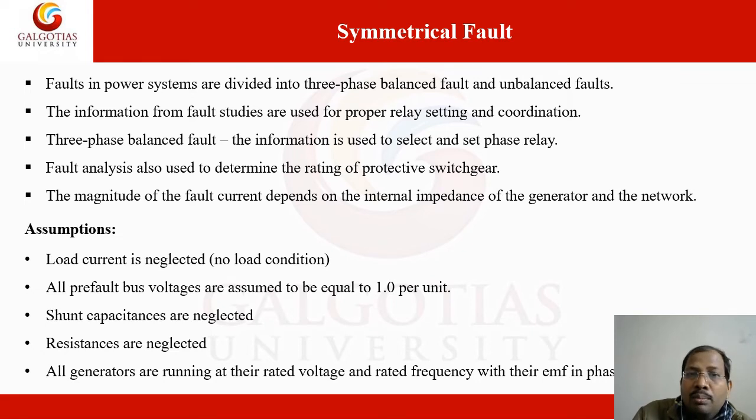For three-phase balanced faults, the information is used to select and set the phase relays. So we can perform the three-phase balanced fault analysis and get the information to set the phase relay settings. Fault analysis is also used to determine the rating of protective switchgear like circuit breakers and other devices, measuring devices.